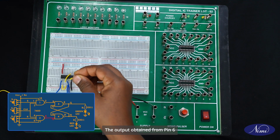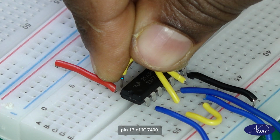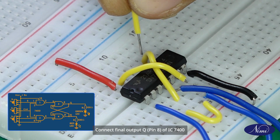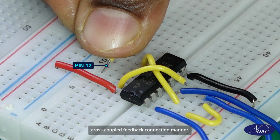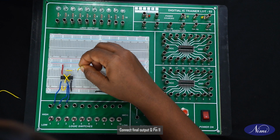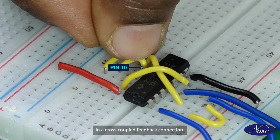The output obtained from pin 6 of IC 7400 is connected directly with input pin 13 of IC 7400. Connect final output Q, pin 8 of IC 7400, to the input pin 12 of IC 7400 in cross-coupled feedback connection manner. Connect final output Q bar, pin 11 of IC 7400, to input pin 10 of IC 7400 in a cross-coupled feedback connection.